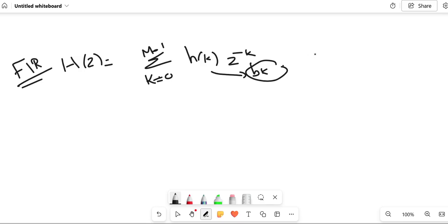So, what are the different window techniques? How do you convert your infinite length impulse response coefficients into finite ones? Mathematically, by multiplying h_d(n) with the window function w(n). All these fundamentals we have seen in the last videos.